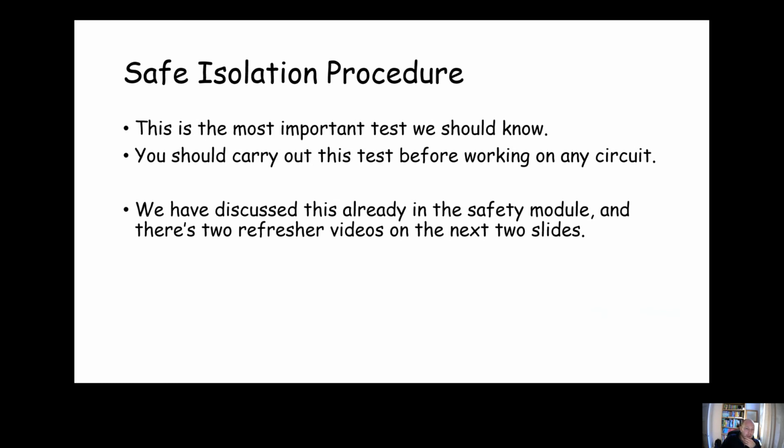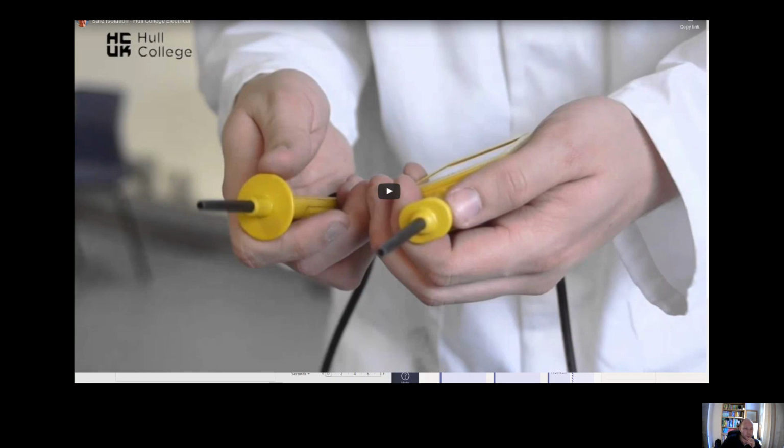So you have to carry out this test before working on any circuit. You have to check that the circuit is dead before you work on it. And there's a refresher video on these. I recommend, like I say, go into the PowerPoint and view these videos, okay?